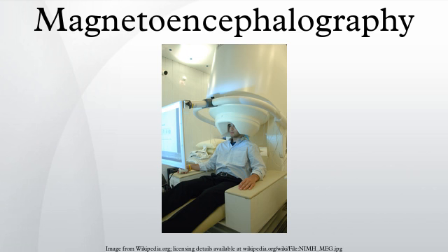Magnetic continuity is maintained by overlay strips. Insulating washers are used in the screw assemblies to ensure that each main layer is electrically isolated. This helps eliminate radio frequency radiation, which would degrade SQUID performance. Electrical continuity of the aluminium is also maintained by aluminium overlay strips to ensure AC eddy current shielding, which is important at frequencies greater than 1 Hz. The junctions of the inner layer are often electroplated with silver or gold to improve conductivity of the aluminium layers.